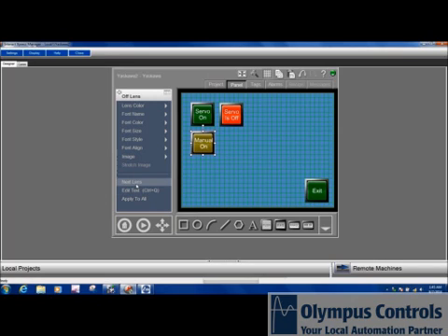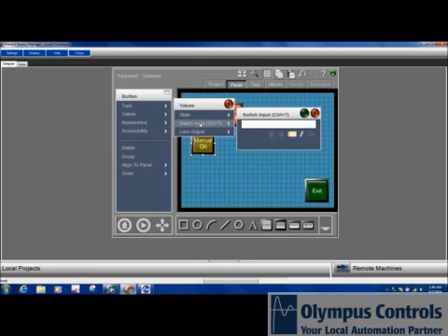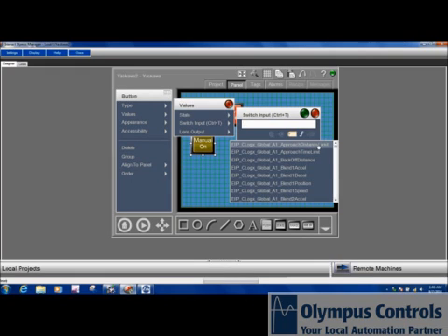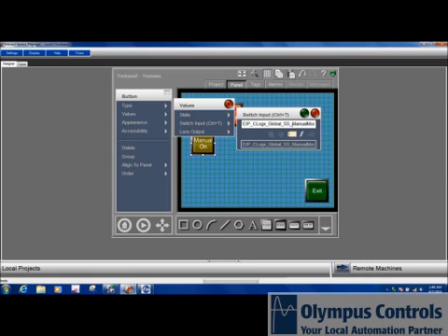On. Okay. And then once I push it in, manual mode will be enabled, so I'll do manual mode on. Manual is on. And let's make that bright yellow with a black font. Okay, so that should allow me to turn on and off manual mode. Let's go ahead and connect that to my manual mode tag. So there's my manual mode tag. Okay, that should be good.